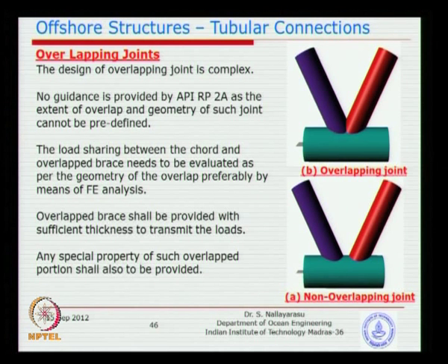Something like this, you can see from here, is a picture that you can easily understand. Overlapping becomes a problem, because if you make this member bigger, then automatically the overlap goes away, and you have to size the braces properly so that that type of overlap does not come up.